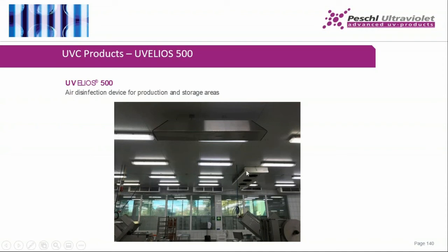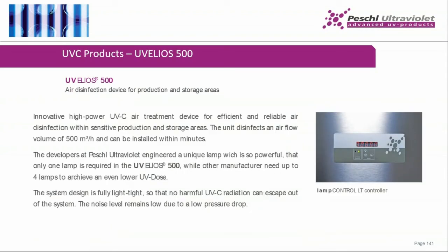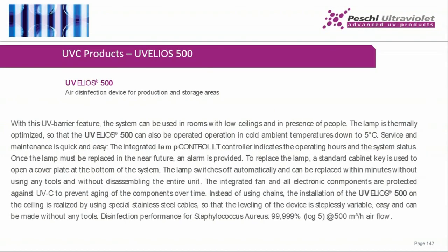There you can see these coolers, and typically this part of the lamella, I don't know exactly if you see my mouse or the pointer. There you can see that normally a UV lamp can be integrated to disinfect the front of these lamellas. Okay, this is easy to use. You have a small touch panel. It is usable for 5,000 cubic meters per hour, and therefore we have to think about whether you want to disinfect 2 times an hour or 3 times an hour. That depends on the microbiological load and the situation inside your company.